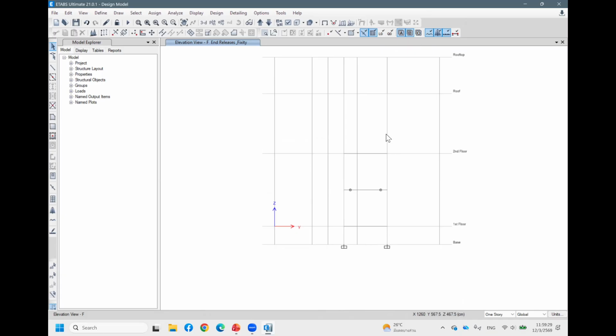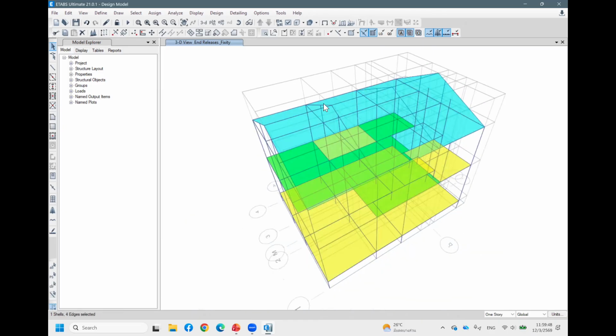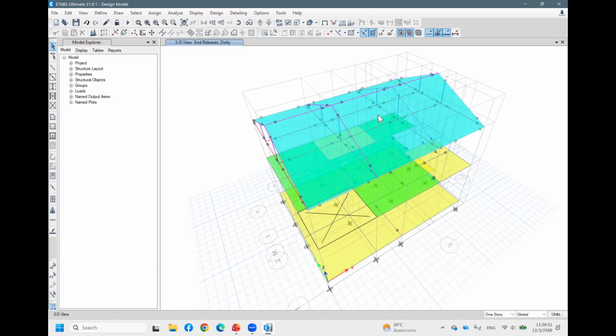Okay, now we already have the second floor. There is no stair from the second floor to the top, so just one beam. Okay, now we have the beam already. So we just apply the load of the stair onto that beam. The next one I want to talk about is the roof. When we draw the roof, if you draw it one sheet by one sheet, it's okay.